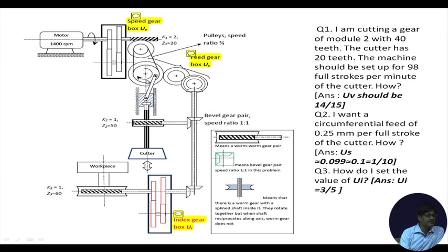Once this pulley is rotating, there is a connecting rod connected with a reciprocating block. This slider slides in these guideways to and fro, and as you can well understand, this rotation causes reciprocation of this block.